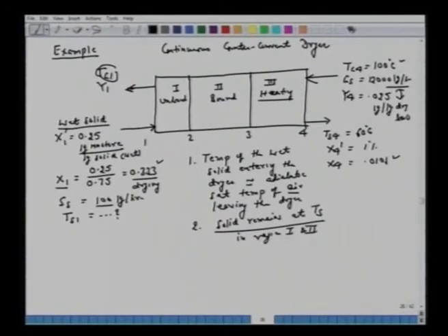Alright, so before anything else, let's discuss what it does mean. If you recall in our previous discussion, we said that when we have a solid brought in contact with hot air which has temperature Tz and humidity Y, the film on this, so if the solid is moist, covered with some thin film, we are talking of this unbound region, the moisture will evaporate, water will evaporate, and the solid temperature will decrease till it reaches an equilibrium with Ts.